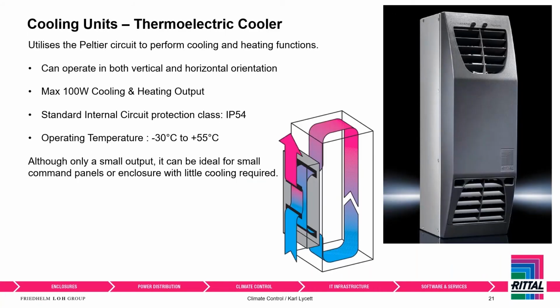Now, we also have what's known as a thermoelectric cooler. So this falls into the cooling unit category, but it also is quite unique because this utilizes what's known as a Peltier circuit, which is basically two electrically charged plates. They're oppositely charged, and depending on how that's programmed, it allows this unit to perform either cooling or heating, which is quite interesting. Now, it's only a very small output. It can only work up to about 100 watts, which isn't a large amount.